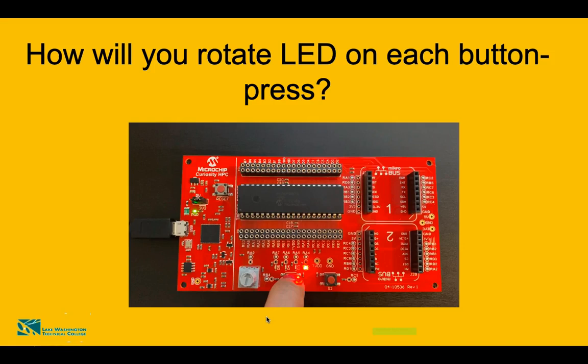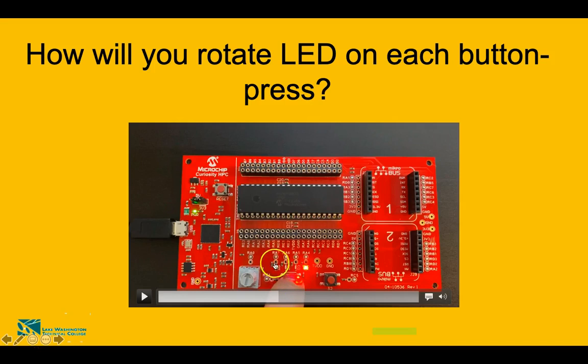And then I want you to carefully observe one other thing in this program: after pressing the switch, when this LED is turned on, which is RA7, then after that there is a lag, and after that lag RA4 is turned on.